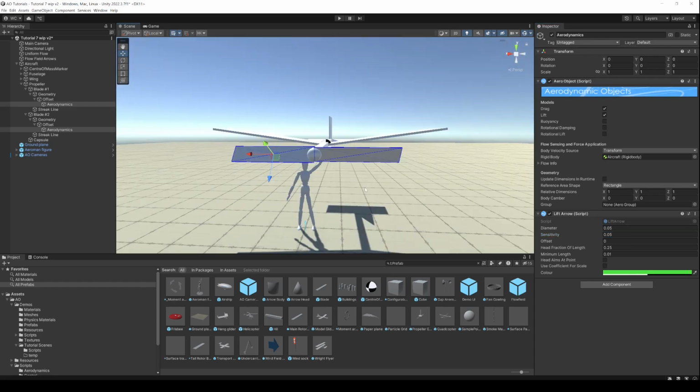What we're going to do next is move the location of the aerodynamic object on each of those blades. The reason is that when you're spinning something around like this, obviously the velocity increases the further you go out. And really this is just to show something about the way the aerodynamic modelling works. The centre of this panel here is where it's going to get its velocity from, so from a physics modelling perspective, it's better to have it further out. Typically on a propeller, you use the 3/4 span point as your control point when you're working out the aerodynamics. So we're going to shift our aerodynamic object out by 0.25 in that direction to get it at the 3/4 span position.